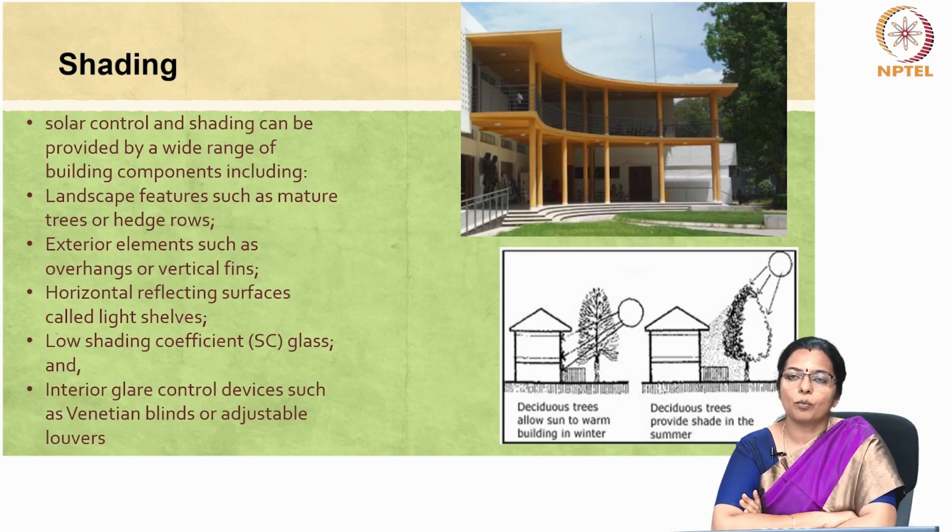For south-facing openings, shading must balance, allowing low-angle sun penetration for winter heat gain while blocking it in summer. North-facing openings require shading mainly to prevent high-angle summer sun penetration. East and west-facing openings experience relatively uniform solar radiation throughout the year compared to north and south facing ones. The intensity of solar radiation is very harsh on the west oriented openings.